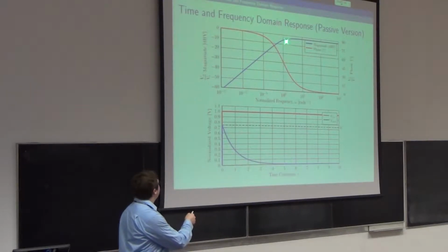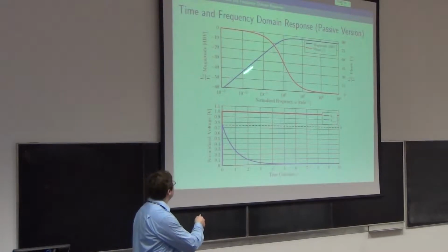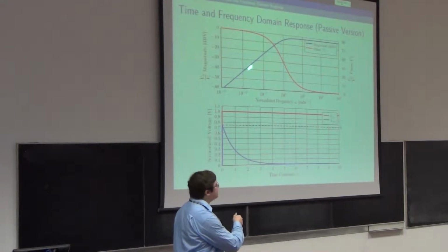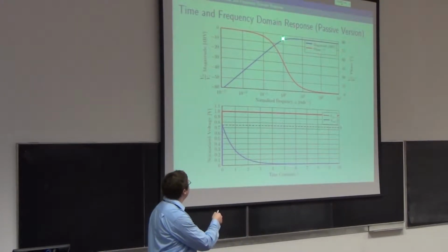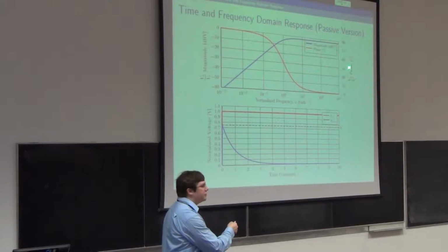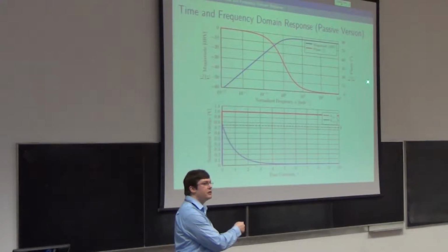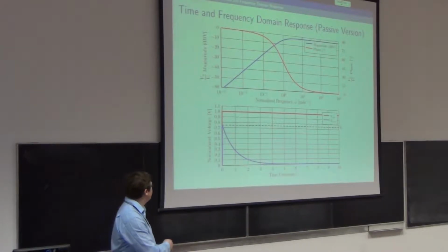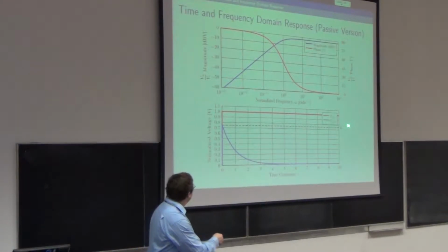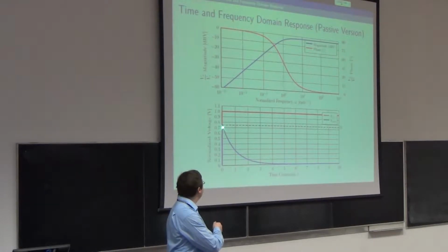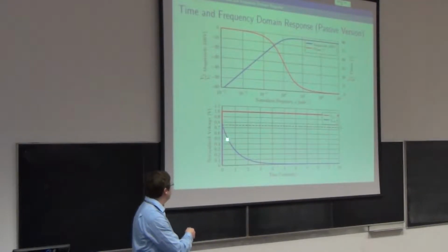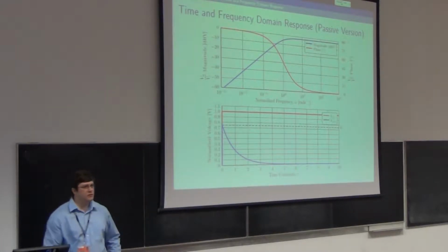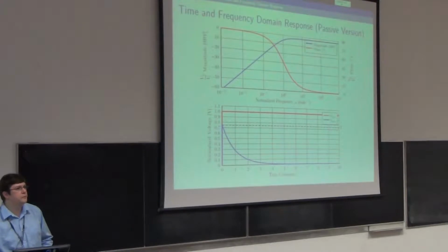So we've got a zero at minus infinity, and a pole here which flattens off this response from its rising at 20 dB per decade. And at that pole frequency we have 45 degrees leading phase shift, so no minus sign. And for a time domain response, we put a step in and we'll find that we have a value of K, which is our frequency independent gain, which in this case is 0.75, and then we have a decaying exponential back towards 0. And the pole zero circuit is just a combination of these two.